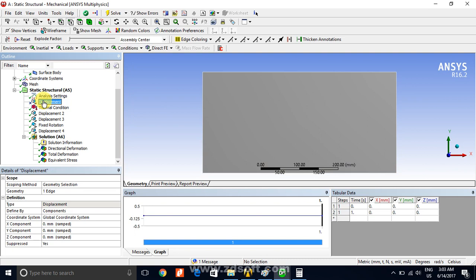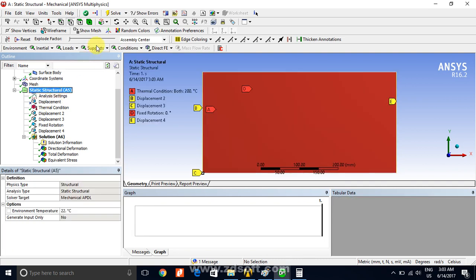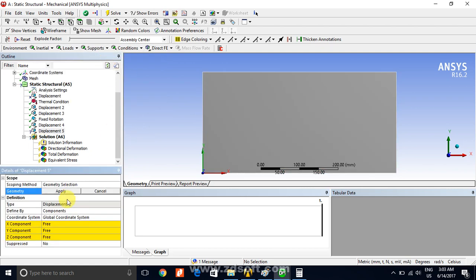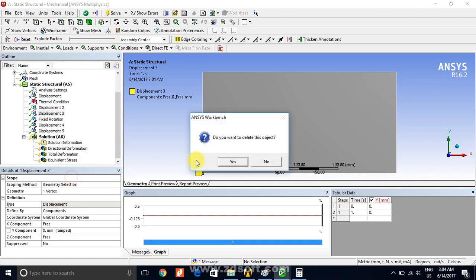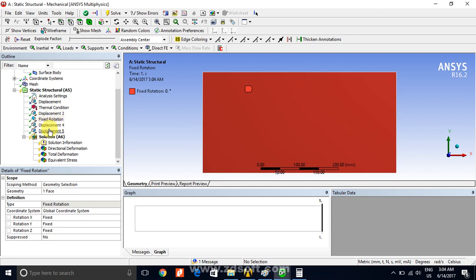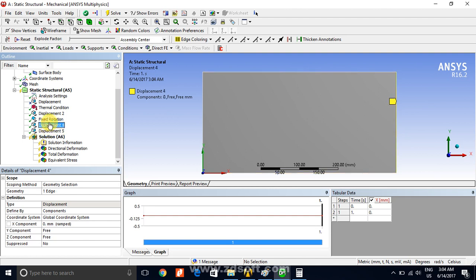But the scene would be something different. What is going to happen? It is displacement. Pick this boundary and keep y at 0. I think we should take this edge also as y equals 0, and this is x equals 0. This is again x equals 0, and this is not needed because we have also done it in x. This is in y direction, this is in x direction. Now solve it.